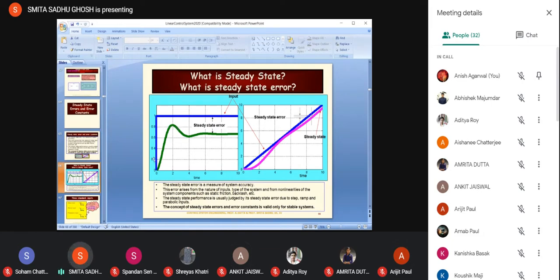So here I have applied a 1 unit input on the left hand side, and I've got a transient characteristic which settles to the steady state value. Now, if the system is linear and my input is not 1 unit but 2 units, the output is going to be doubled corresponding to that input.